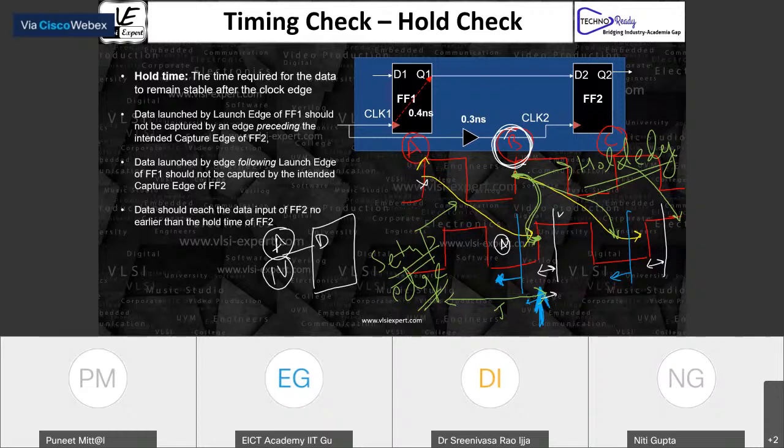What happens if we violate the setup and hold timing? We will discuss that, Surya. Third edge is 28 nanosecond minus setup, 33. Yes, but again, Surya, for which data are you talking about? The data which is going to be launched at 20 nanosecond. Again, 28 and 20, it is 8, and 33 is with respect to 30. So everywhere, the relationship is the same. From the time point of view, maybe it is 28, 38, 48, but the relationship is same.